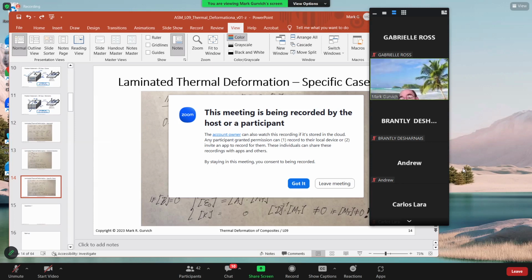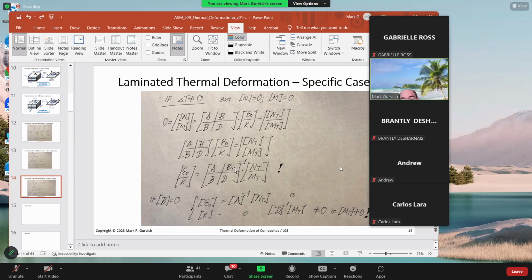It's exactly the opposite. Originally it was at elevated temperature. Just after fabrication, you remove it to room temperature and it starts to buckle, shear, etc. It's a relatively big issue in manufacturing of composite structures. To address it, people specifically modify the design to be sure it does not happen, and if it happens, it is minimized.